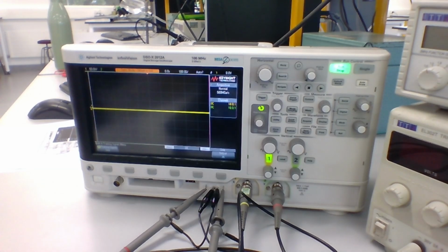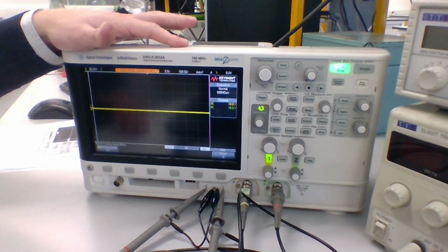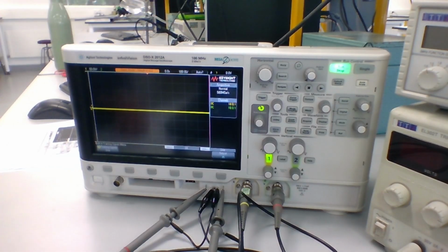It can do this to some extent, but this does have its limitations. It can only really do this for signals that are large enough, so nothing too small in terms of voltage or current. Anything that is consistent, so a nice sine wave, for example. If you're dealing with bursts, digital communications, digital logic, things like that, auto scale will not be able to do that for you. So that is one option.